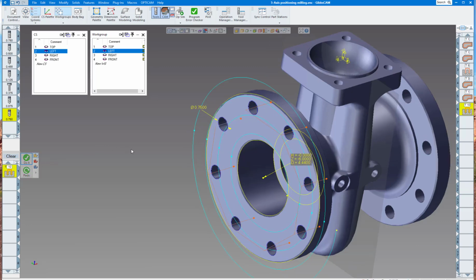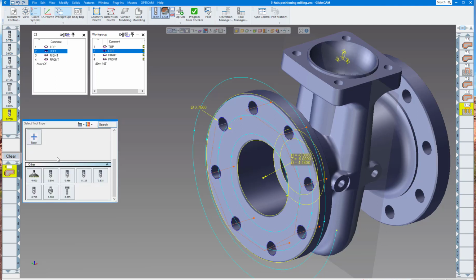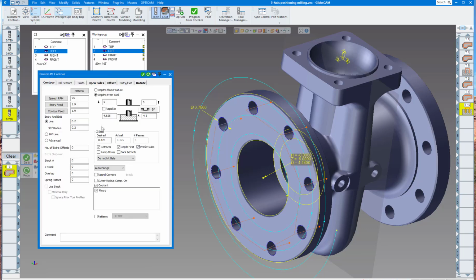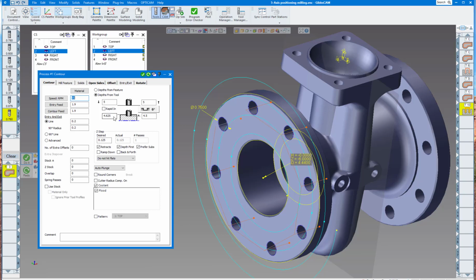Now the last thing to finish would be the chamfers on here. I'm going to clear this out, put a contour in there with our chamfer tool. And again, make sure you're on the left side. Everything else is pretty good there, but I need to bring the tip down inside there in order to chamfer. So I'm going to say we'll say 3.380.